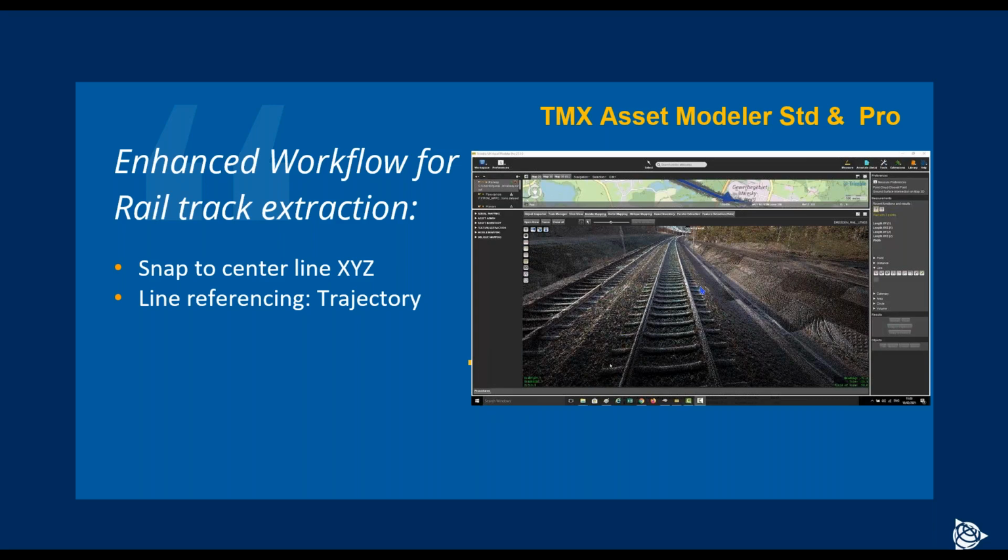And also now, this tool can be running along a reference line. It could be a vector or it could be a trajectory. In my case, I think that trajectory makes more sense because it allows me to follow exactly the trajectory of my movement, the way the vehicle is moving. And that means that in case my rail is coming in 2 directions later on, the tool is not getting confused. And with this line referencing, it's now possible to extract longer linear objects, longer rail track, than was possible even before.